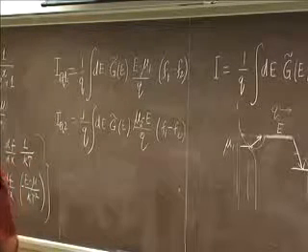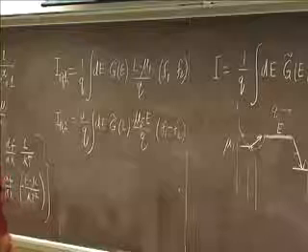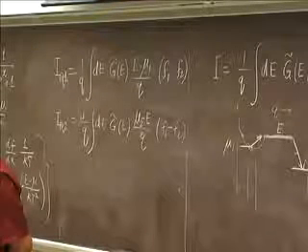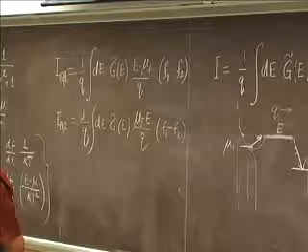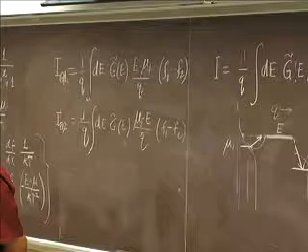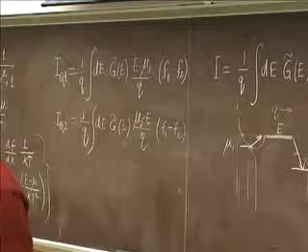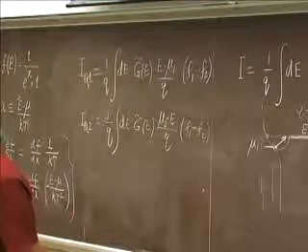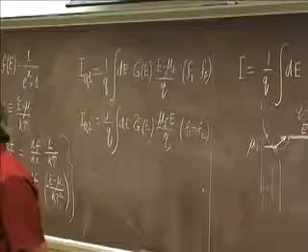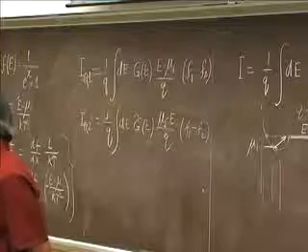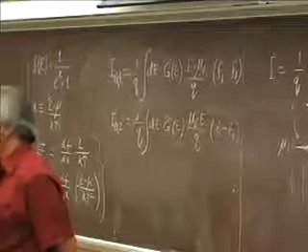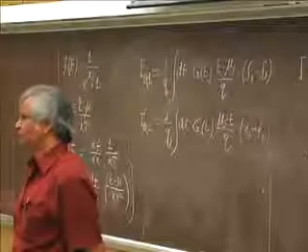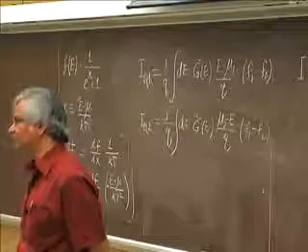So for a very linear system, current flows around the Fermi level. So for that, the heat current is 0. If the density of states above and below are almost the same, that is true. Which is why semiconductors usually make better materials for all this than metals. Metals also have some Seebeck coefficient, some Peltier coefficient.